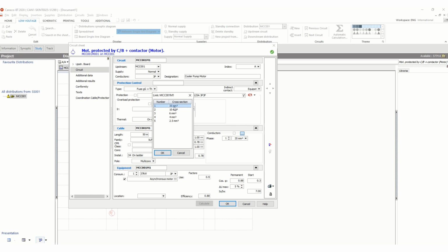Suppose for this motor terminal box, depending on the installation situation at site, the cable tray or the cable routing arrangement, this 35 square mm cross section is not possible there, or due to the unavailability of provision to terminate a cable of this size, maybe you need to consider a lower cross sectional cable, but in that case the number of cables will be more.